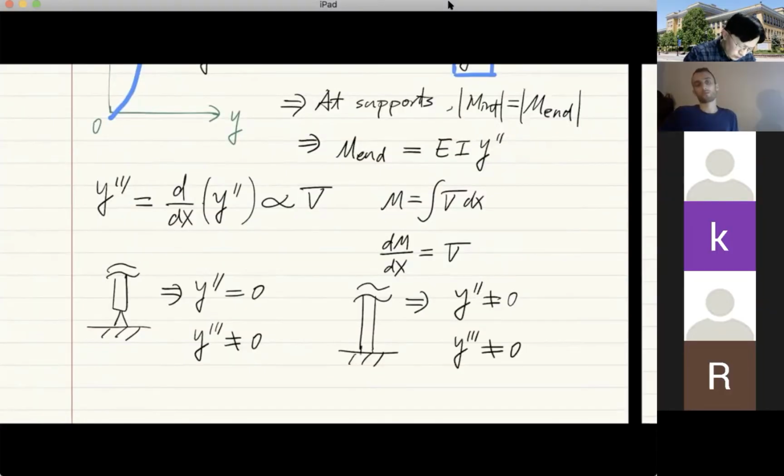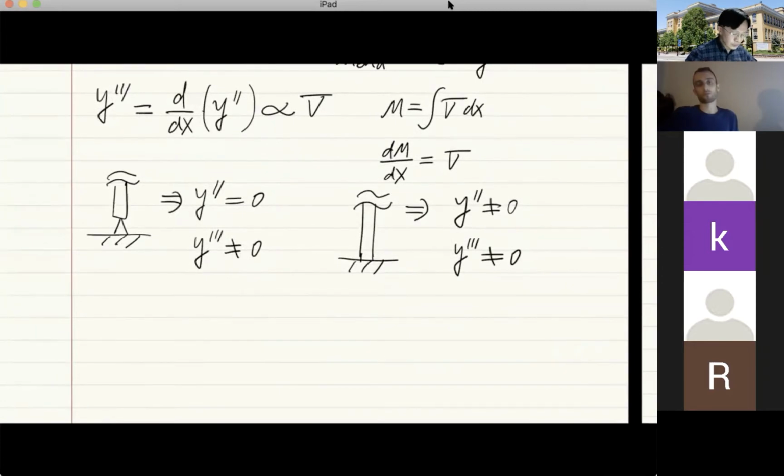Now you must wonder, why do we need to know the force boundary condition? Well, what if you have a cantilever beam or cantilever column, just like one of the columns that we studied in the past, remember? There's one example where the force is applied at the cantilever, which I think is example 9, right? There are two P's acting on basically a cantilever column. So in that case, that means there's actually a free end. So this is a free end. That means there's nothing. In this case, if it's a free end, the second order derivative is what?